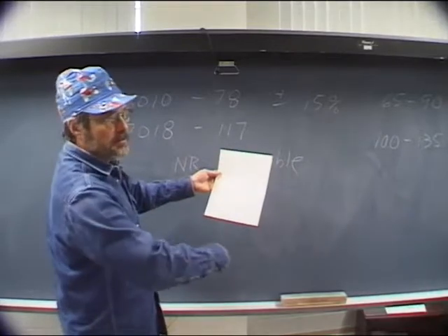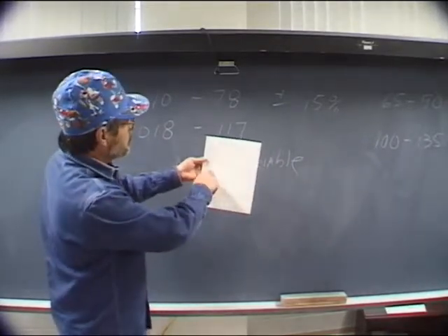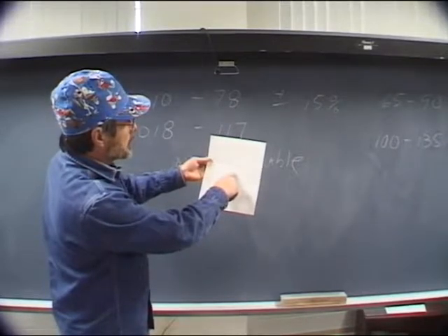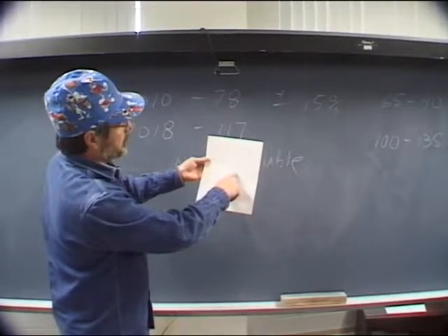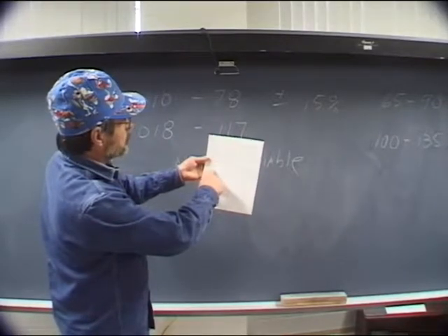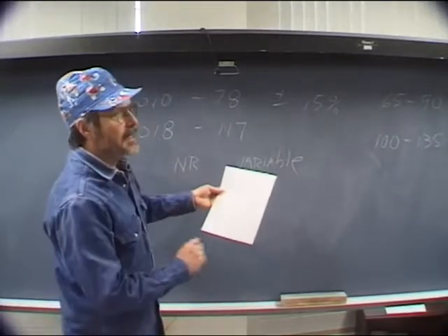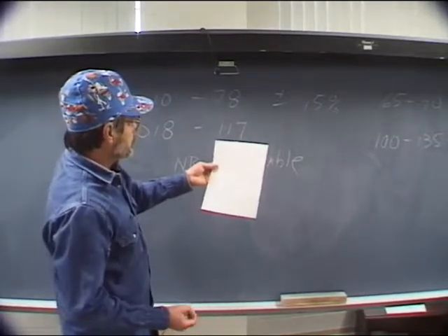Was it pure tungsten? Was it 2% thoriated tungsten? Whatever, that would be going in there. If we use gas metal arc transfer, it's asking if so, did you use spray arc or short circuiting, whatever. And then the electrode wire feed speed range, blah, blah, blah. But of course, all of that information is not applicable to our little scenario.